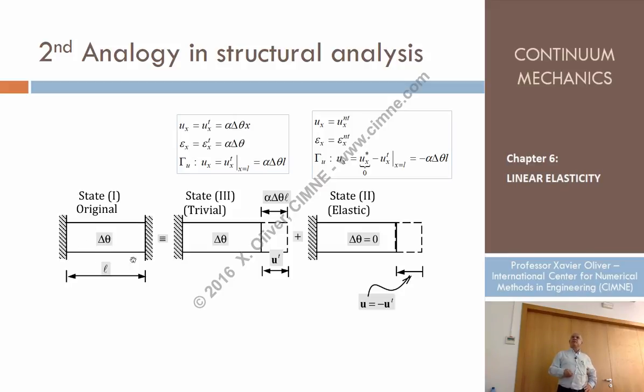Imagine that you have this clamped, double clamped at both ends beam subjected to a constant increment of temperature, right? Our knowledge of structural analysis said, well, to solve that, first we release, for instance, this side so as to make the structure statically defined, what we call isostatic. So now that is a cantilever. Let the structure deform in terms of this delta temperature.